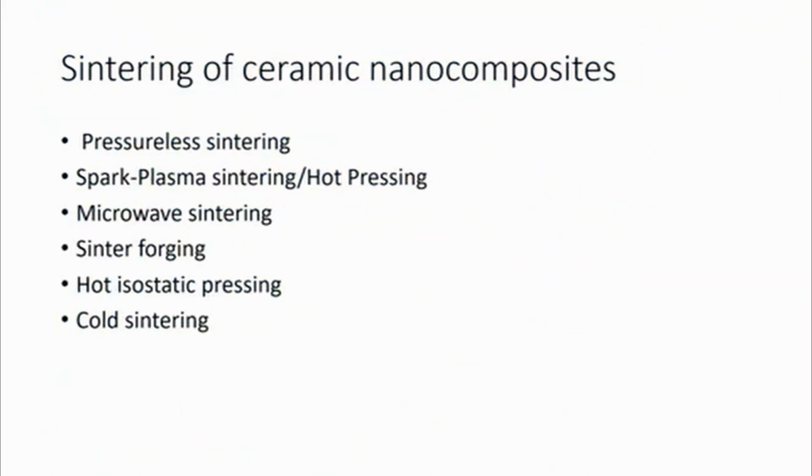To fully exploit the distinctive properties of bulk nanocrystalline materials, nanometer-scale powders must undergo densification to attain specific properties, geometry, and size in their final parts. The critical aspect of nanopowder consolidation lies in achieving densification while minimizing microstructural coarsening and undesirable transformation. Notably, controlling grain growth during intermediate and final sintering stages, as well as preventing Ostwald ripening, is essential.